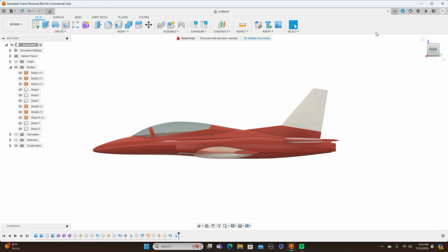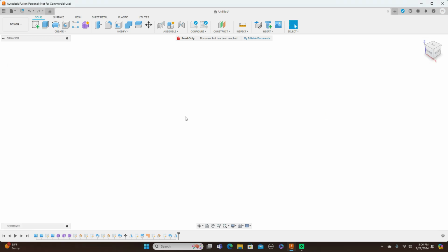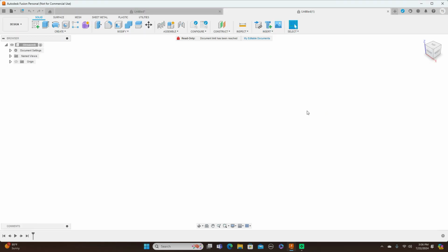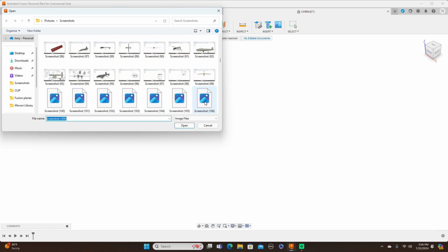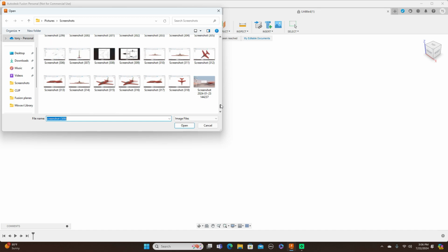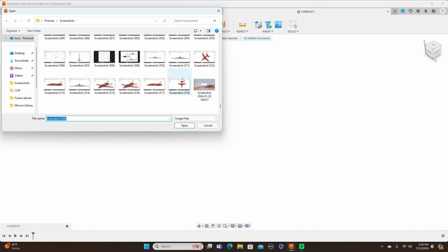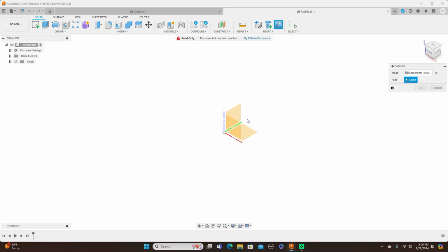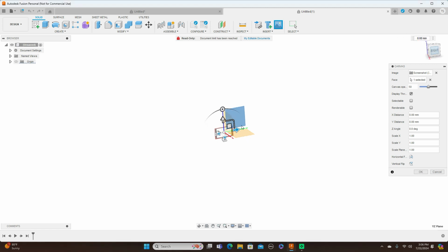All right, let's go ahead and get started here. So I'll just create a new project or new design. And I need to put some pictures in here, so I come up here to Insert, Canvas, and the picture's on my computer, and it should be a screenshot. That's it right there. Open that. I want to put it on this plane here, so I click this plane and click right here so I can see the right side and drag this out.